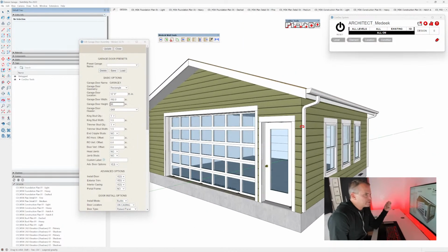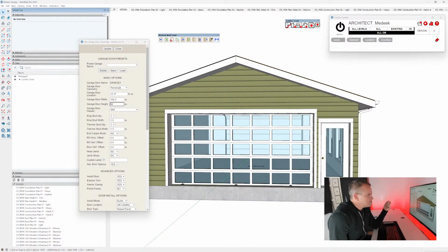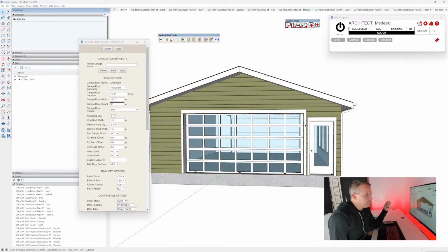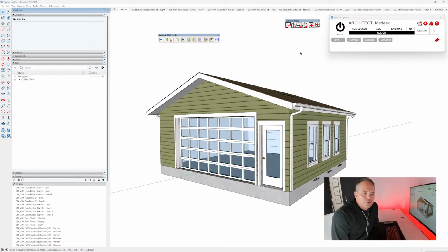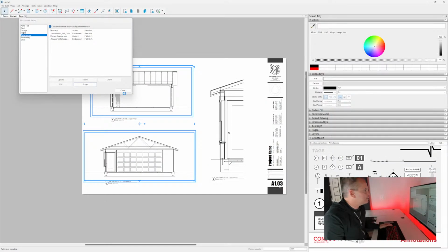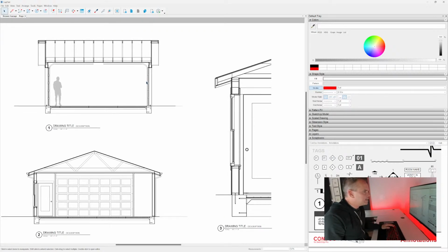And then, like I was saying earlier, this way all my man doors and windows line up, and I think it is okay that that's higher, but it makes me a little crazy. That's okay. All right, so now here's where the magic of the live sync comes in. When I open my SketchUp model from LayOut, I'm going to save this, bam, and then hop back into LayOut, and there it goes. You see that? It just jumped up. So now we've got our updated model.